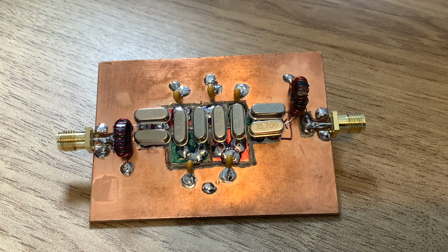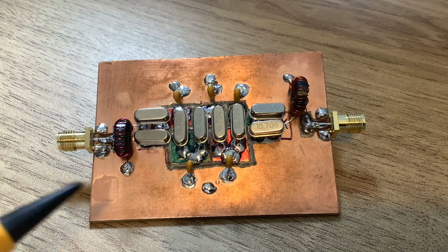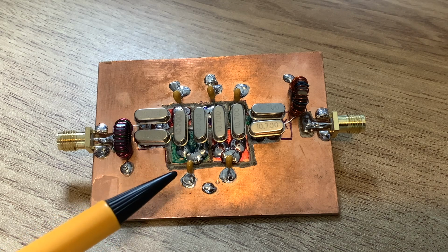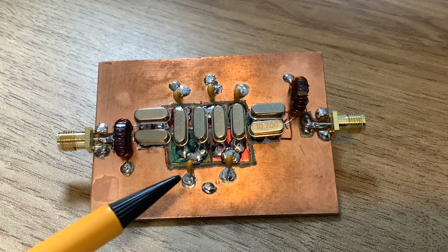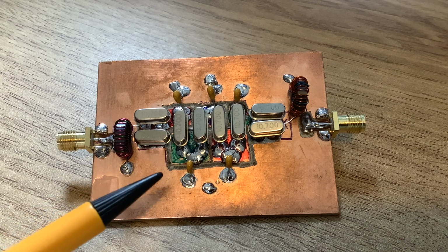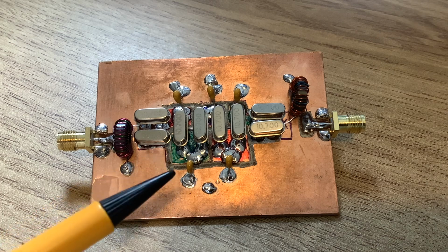And what I soon discovered is that as you increase the bandwidth of this filter, not only do you need to decrease the value of the capacitance, which I'm down to about as low as you're going to get really, 6.8 picofarads these are, and obviously there's not much more room to maneuver there, so pretty soon you'll be maxing out what the practical bandwidth of this thing will do. But anyway, so 6.8 there.